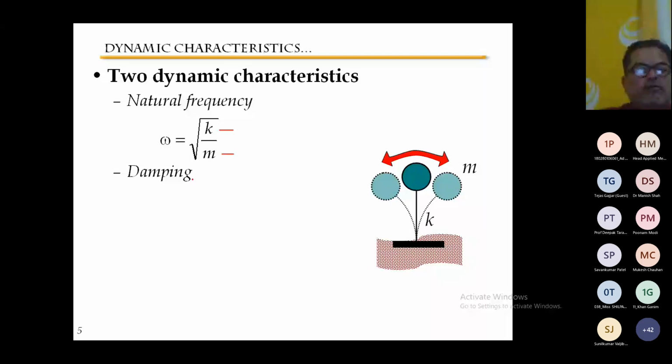So, what we can conclude is that a low-rise building has high frequency, and a high-rise building has low frequency. Right. Now, we know another phenomenon, that is resonance. Resonance means the frequency of a system matches the frequency of the external excitation force. If these two match, then the system will exhibit a very large response, right? Or larger displacement will be observed.